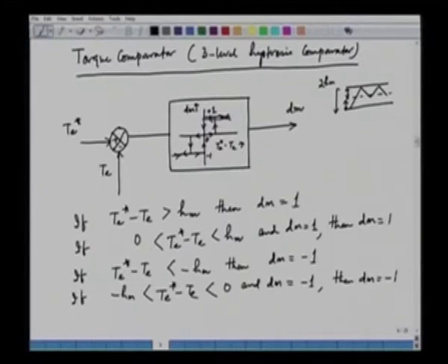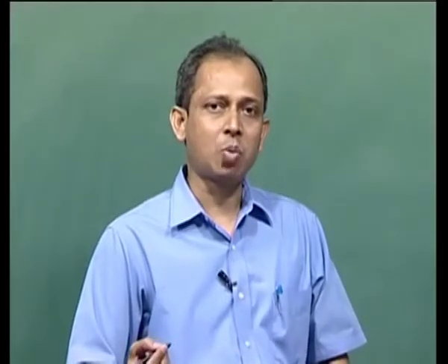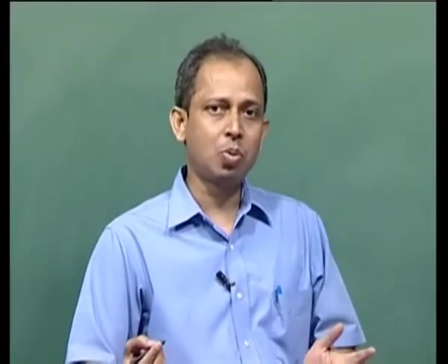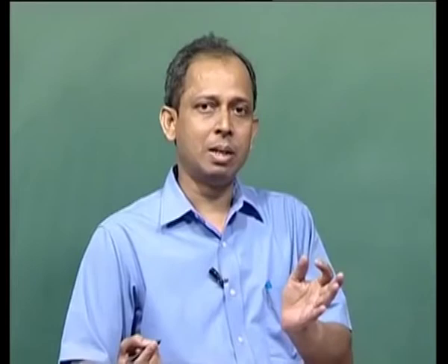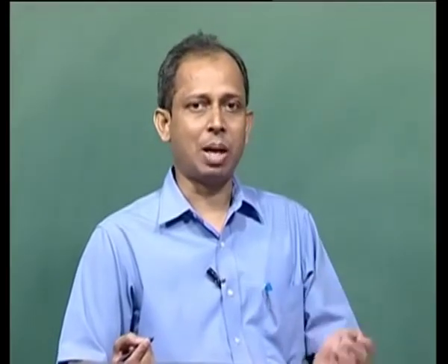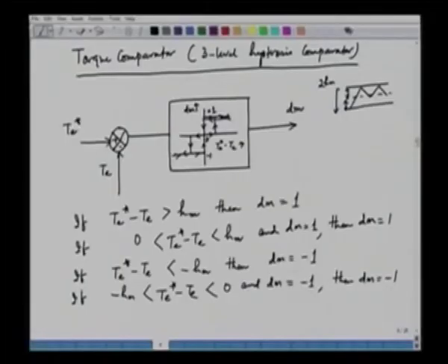It means in the lower band, if the torque status is minus 1 and it comes to the lower band, the torque status has to be maintained as minus 1. So, we are basically travelling along this line. Here it is minus 1, and if it goes into this particular region, this will also be minus 1. And then we can have other statements for this implementation.